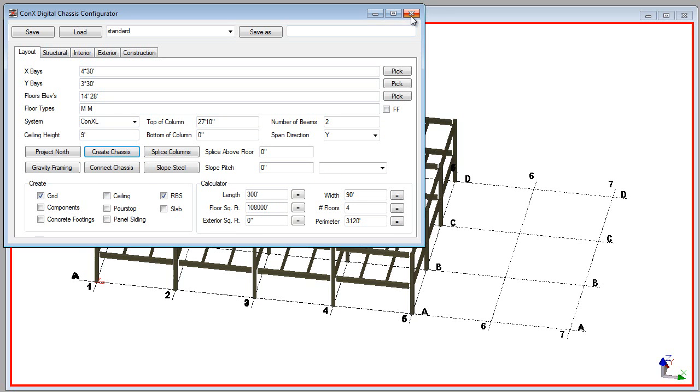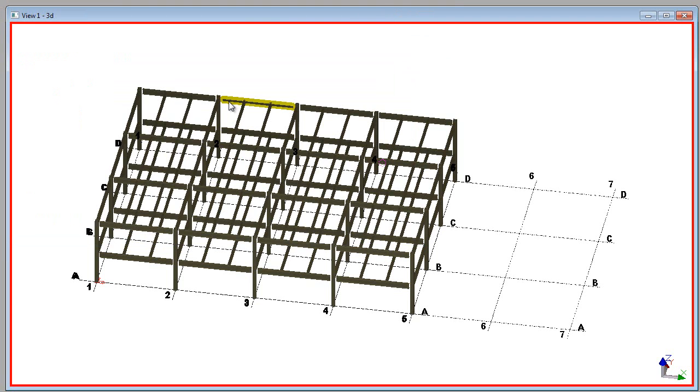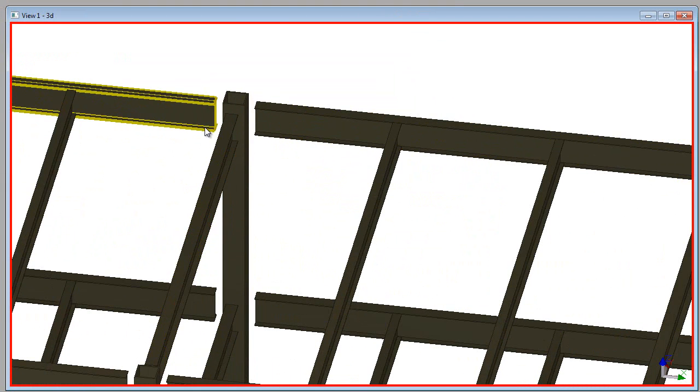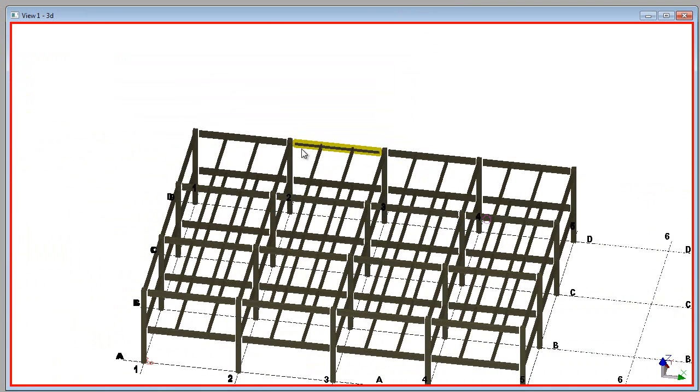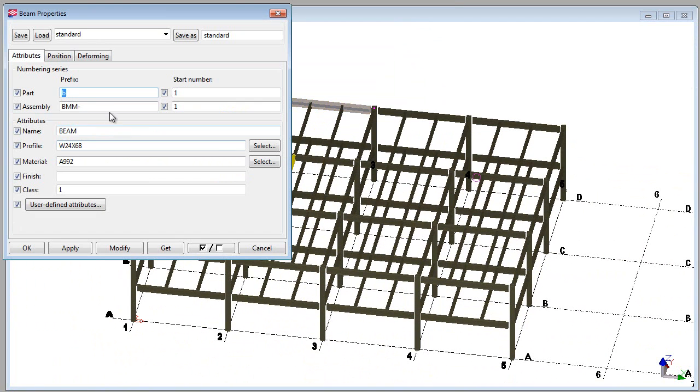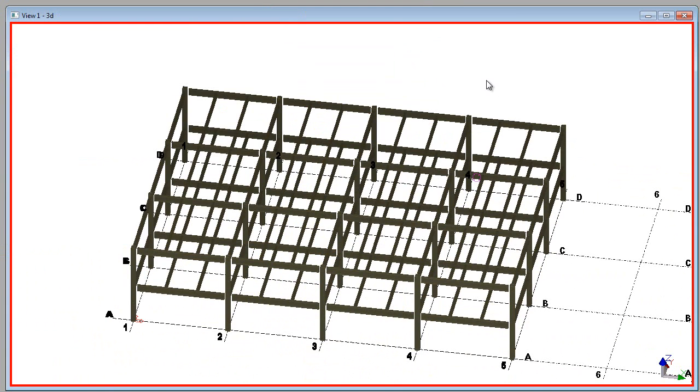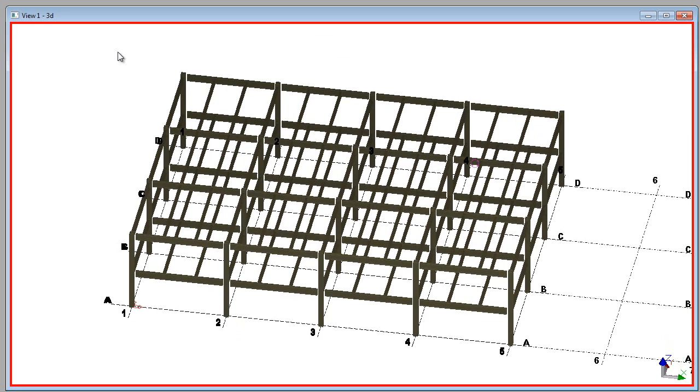And within a few moments we have all of the beams and columns that we want to work with for an advanced bill. All of the setbacks are correctly applied for the connections that would be there. So if we open up the properties, we have the member size here, the material grade, and if you wanted to, you could even assign the material to different phases in the phase manager, which would be like your erection sequences or your construction phases, and that will go across in the bill of material export as well.